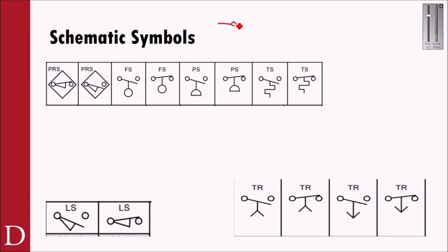One of them would be something like this. This would be just a switch or a toggle switch. The other one would look like this, which I would call a normally open push button. And another one that would look something like this, drawn from underneath and connected, would be a normally closed push button. I think everything you see on here right now is everything that you could possibly be asked on the test. So this I would call a normally closed proximity switch.